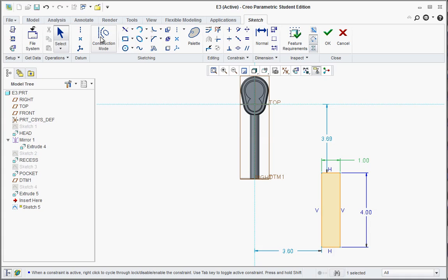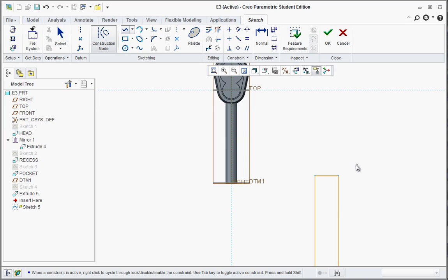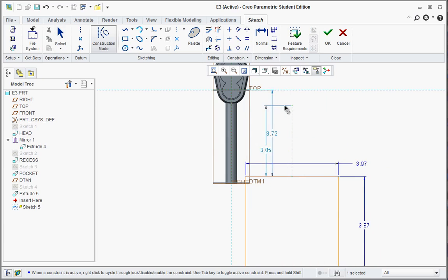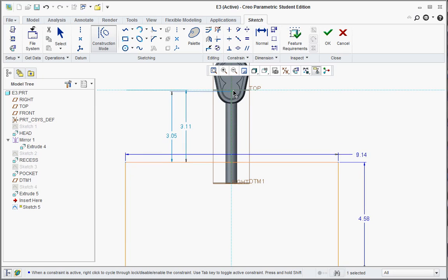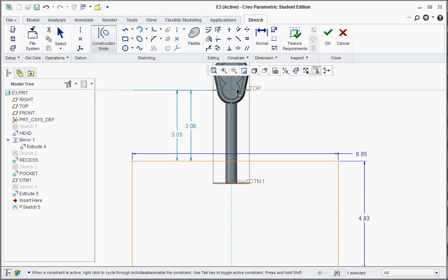Now what you can do, you can actually take construction mode here and draw a line at the midpoint. Look at that, that little M. So once you select the line tool here, construction mode, you could draw from the midpoint a center line vertically. Now the length doesn't matter so much, just go ahead and draw that out. But now middle click a couple times and grab that center point and drag it, and we want to actually lock that into the origin here.